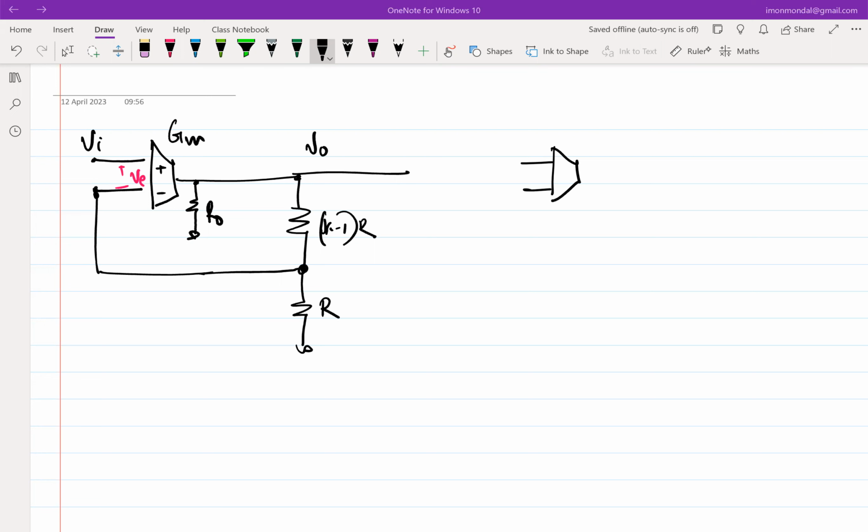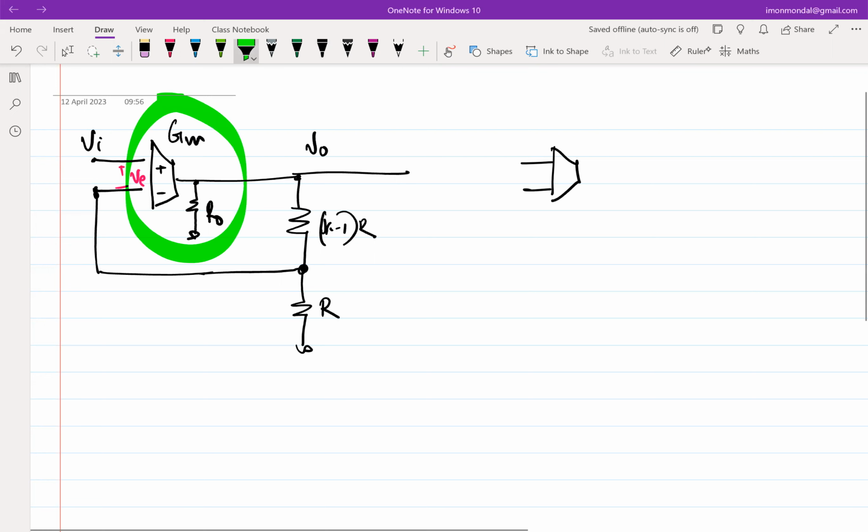because ultimately we want a high gain amplifier because we want to get a stable gain when we put it in negative feedback, right? So obviously by now you should understand the fact that even though we can get, let's say, in principle, infinite gain from this contraption theoretically, or very large gain, that gain is not fixed in terms of, if we are trying to get a very good gain which is invariant of temperatures and ambient conditions, right?